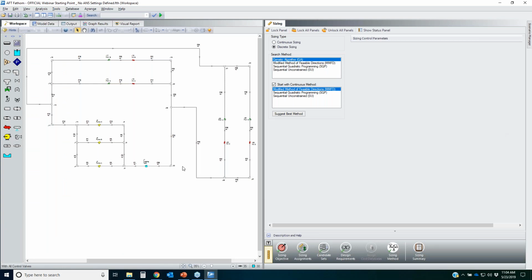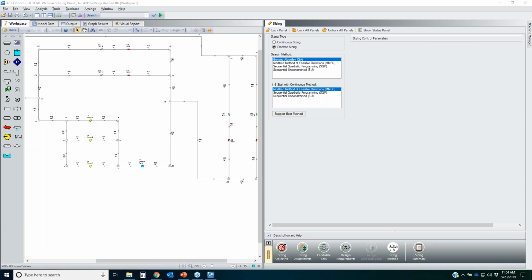As you notice, I have tees, elbows, heat exchangers, valves, and pumps. There's no way to determine the weight for any of those different components. So when you're doing a weight sizing process, it's piping weight only, but it's going to give you a very good first cut at your design when you do not have any monetary cost information yet.